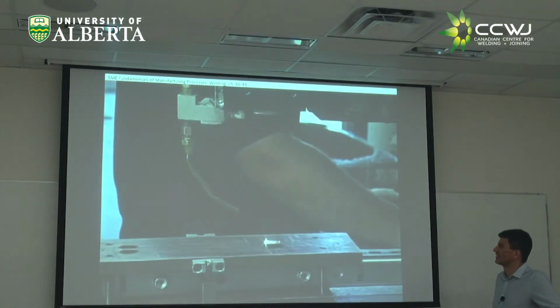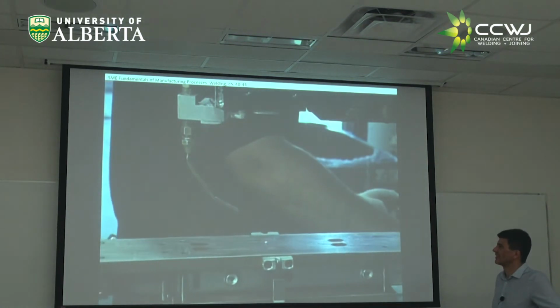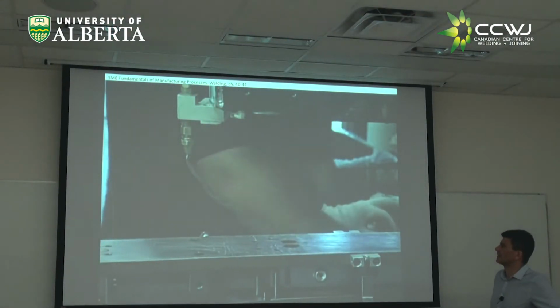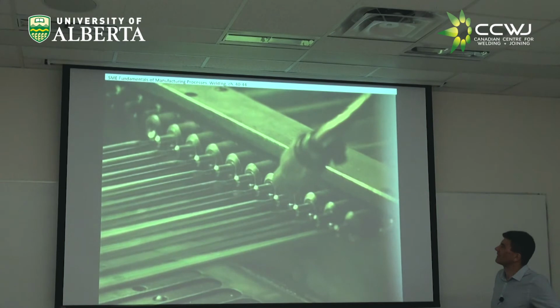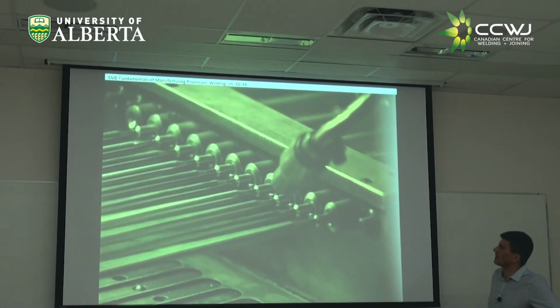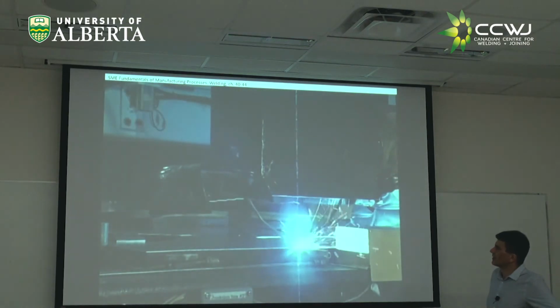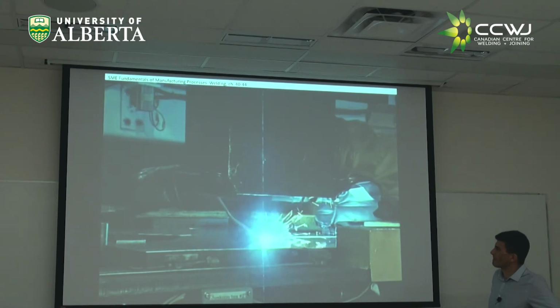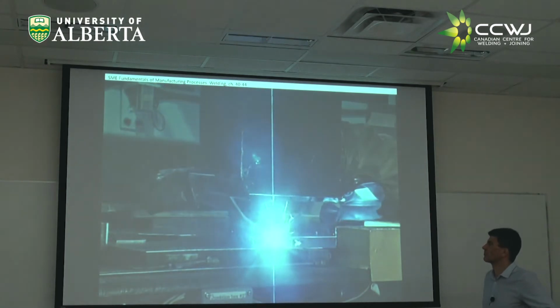CO2 lasers can generate greater continuous beam power and are suitable for welding thin or thick workpieces. YAG lasers generate less continuous beam power and are generally used to weld thin workpieces. Most laser welds require no filler metal, although filler metals can be used if desired.